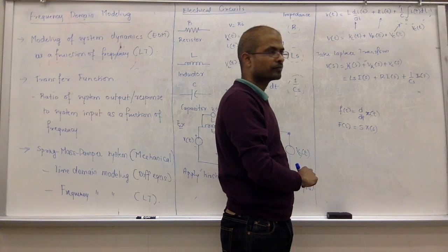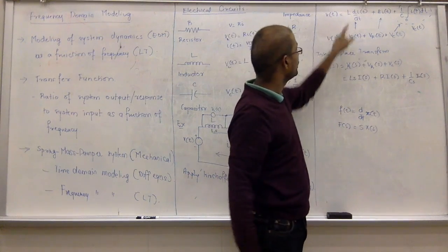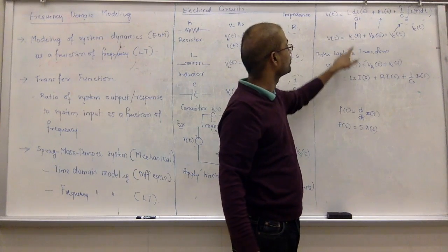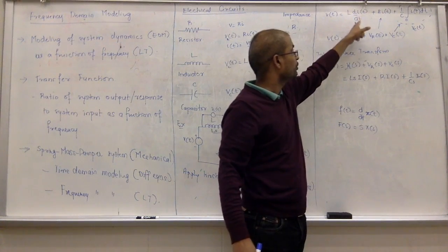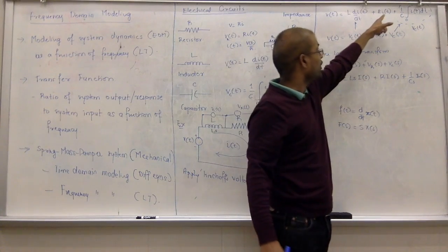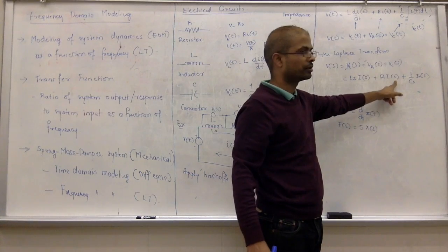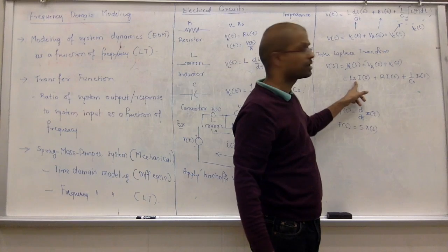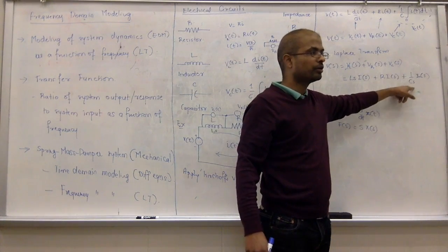Remember, just recall this. You are applying exactly the same. Your V L of s is this. V L of t is this. So we are just expressing this as V L of s. But what is the Laplace of this? L is constant. Since it's di over dt, you get s into I of s. Here it is r into I of t, right? There's only r. R just comes out of it. Here, since it's integration, see there is a differentiation, s is added at the numerator. If it's an integration, s comes to the denominator.